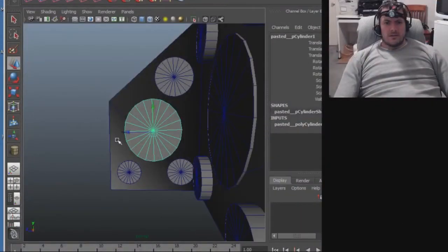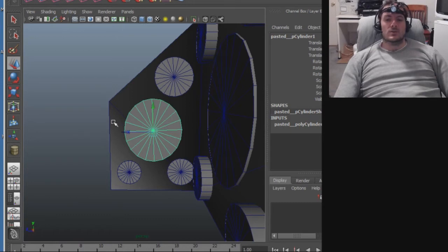So now only the areas that don't have the circle are going to be printed. So this is going to print, this is going to print, and these shorter sections horizontally, when they shrink, they're going to pull in on the curves of the circle. They're going to pull this way to the left. And the circle can handle those forces, and it won't be transferring those forces to the lower layers. So if you pull right here, that's just going to cause the circle to widen. It won't affect these layers, so it won't rip them up.